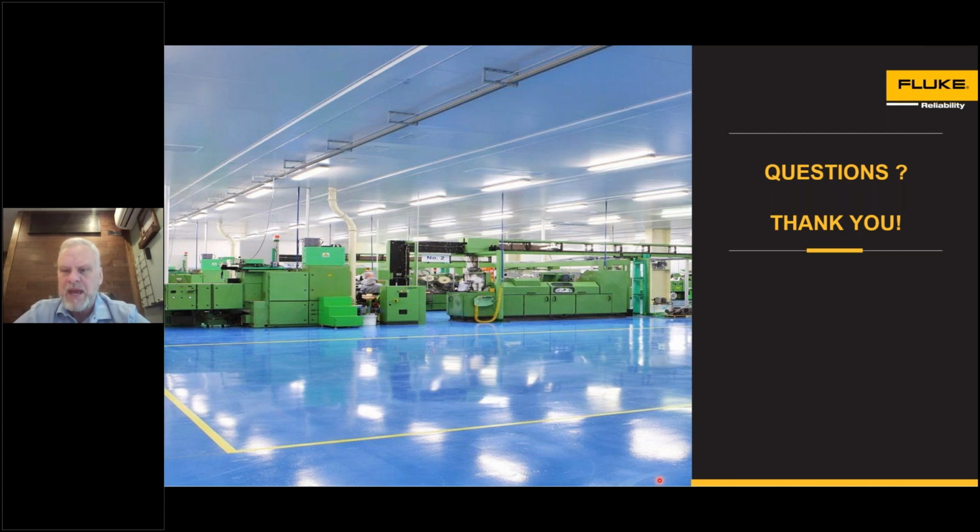And again, they both have their advantages and disadvantages. There's a big cost advantage of wireless over wired systems. Route walk-around systems are still the least expensive altogether, but wireless over wired online systems is still quite a bit cheaper and gives us that hourly and daily data that gives us a lot of consistency around the results and understanding of the machine running, and when it's in fault, how that fault is progressing. I don't know if that answered your question, but that's to the best I understand your question. Thank you. Okay, thank you.